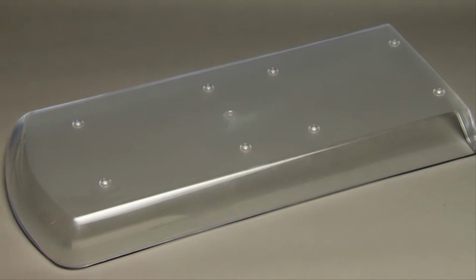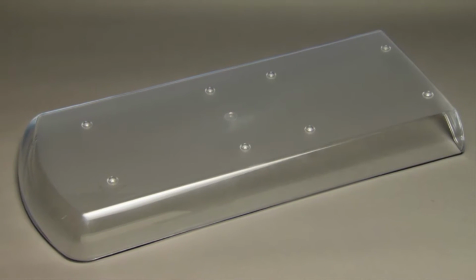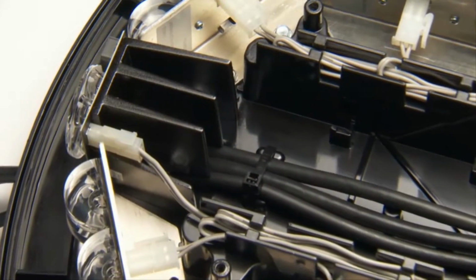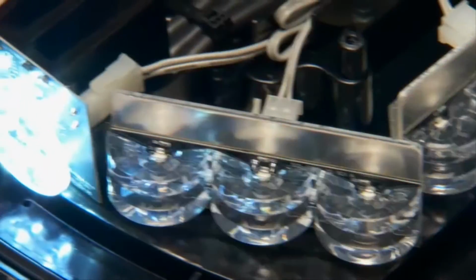Plastics was important for multiple reasons. On the base, it was the complexity of the part, making sure it would fill. But on the lens, which is the most visual part, we have to make sure that it fills and there isn't going to be visible flaws such as knit lines or big sink marks that would show up that someone would notice. Plastics allows us to validate that. It allowed us to run all those what-ifs on these complex parts that we wanted to make part of that base.